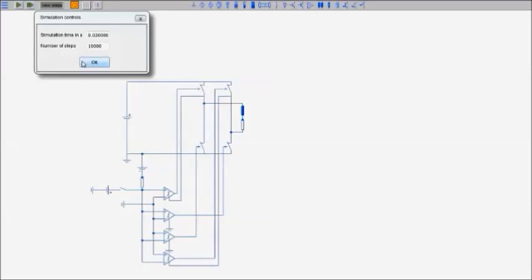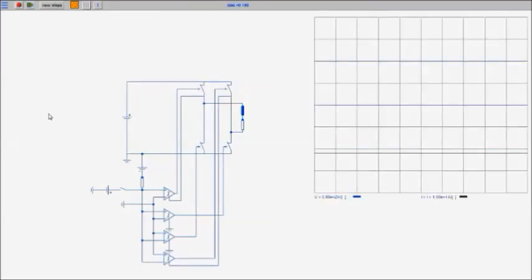This is how it looks like. So still we can remote control the switches, but it's not only one switch as before, we have now 4 of them. And it's always so that these 2 switches have to be basically on at the same time, whereas these ones are off at the same time, or vice versa. These ones are on and these 2 are off. They can never be closed at the same time, otherwise you would have a short circuit.